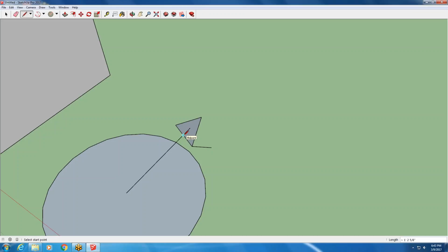Midpoint. So we've seen end point, midpoint. Sometimes you can get, if I escape out, on edge, from point, on face. These are all called inferences. Where we have O snaps and snaps in AutoCAD, we have inferences in SketchUp. And these inferences are the same thing.